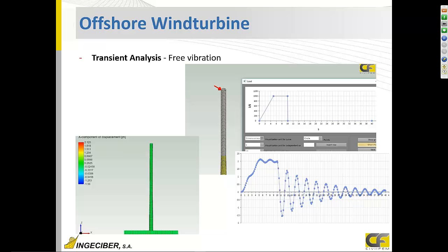In this sort of analysis, we can have a gap in that zone. Also, we can model nonlinear soil analysis and have much more detailed results. And nonlinearity as well for tower material. For steel, we can set a bilinear to take into account a possible yielding or collapse of the structure. Later we will see how to do it.